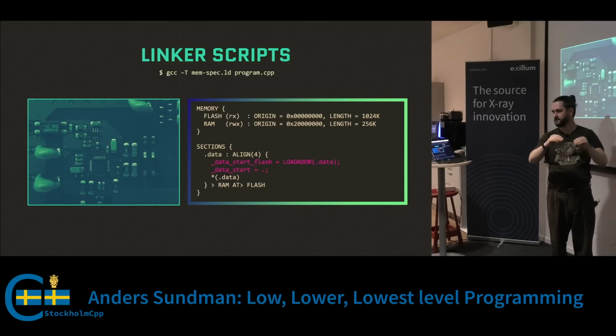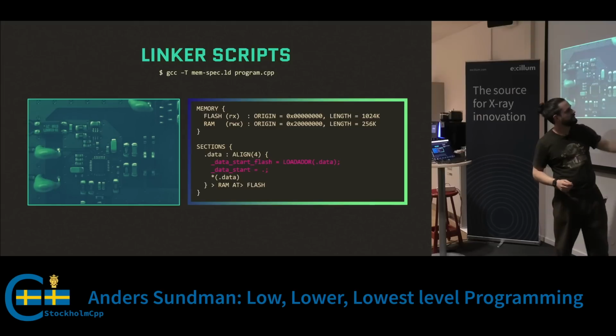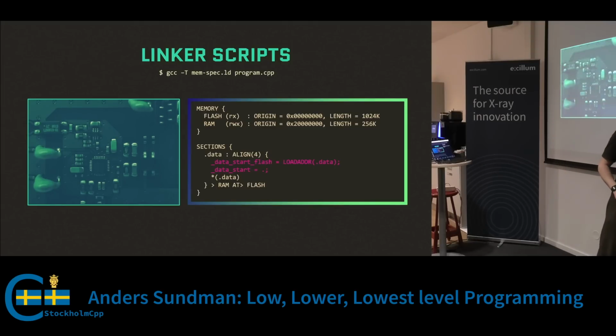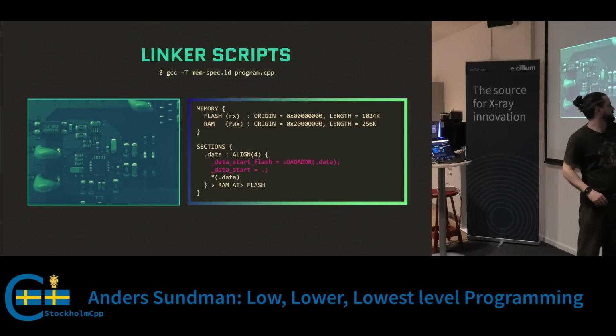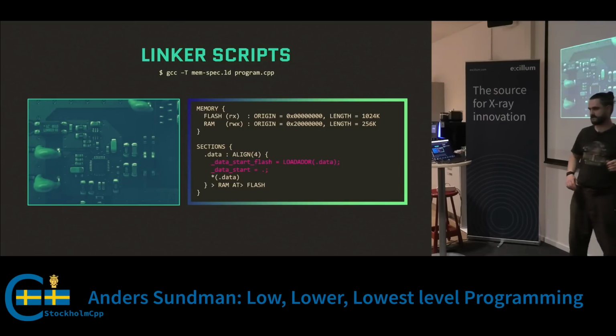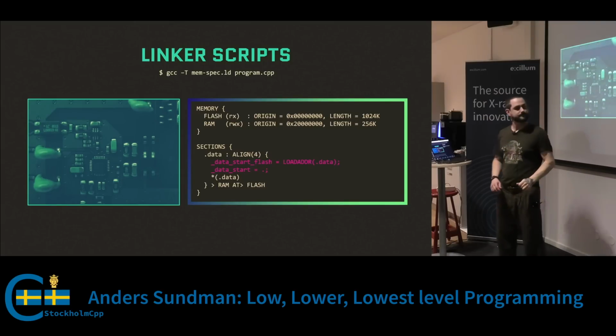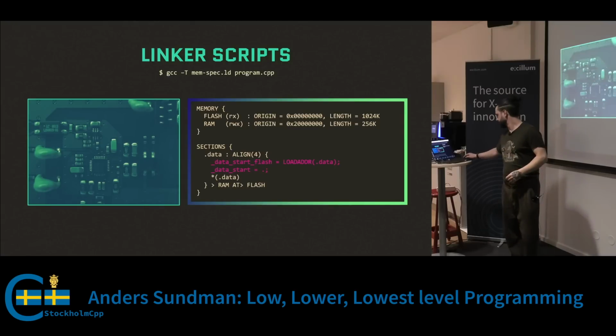And the idea is, in the reset handler, we copy things from Flash into RAM so that all the initial values are available. And you can use this load address of data instead of using the dot, because the dot goes to RAM, and the load address is sort of the start of where this data in Flash goes. So that's the start of the Flash.